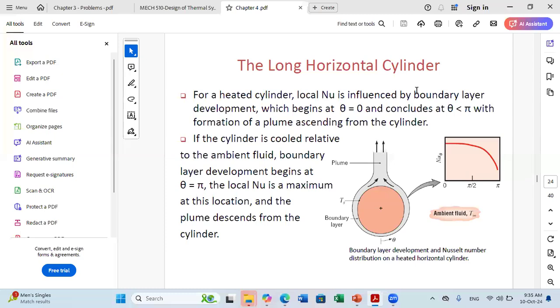So we discussed last time the case of natural convection or free convection, and we have seen that it will be affected by several parameters, including the geometry of the surface, the roughness of the surface, the type of fluid over the surface, etc. Okay? Now, we said that we need to develop some empirical relations to find the convective coefficient H. And we discussed that the Nusselt number is a dimensionless number that will allow us to calculate H. Today we'll do problems to understand this idea in a better way.